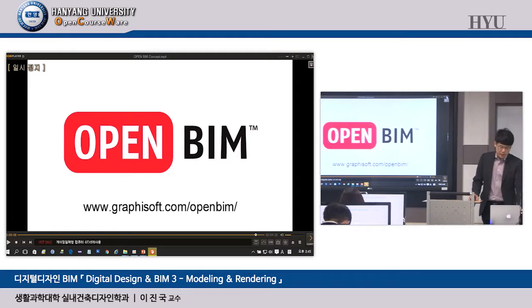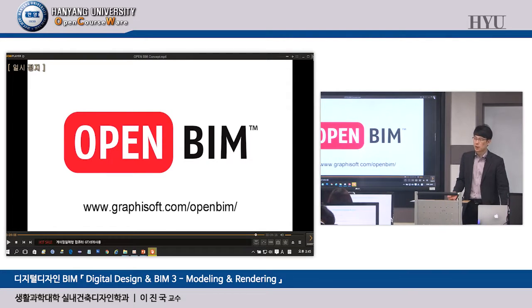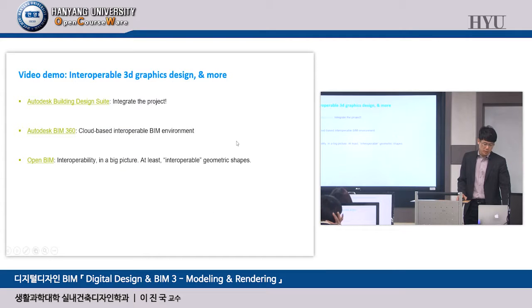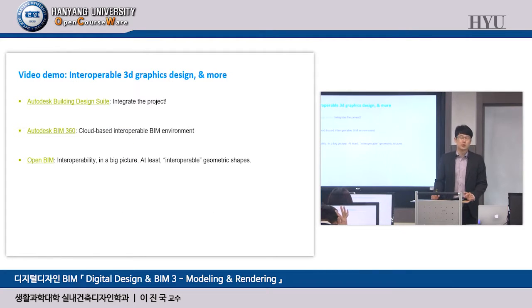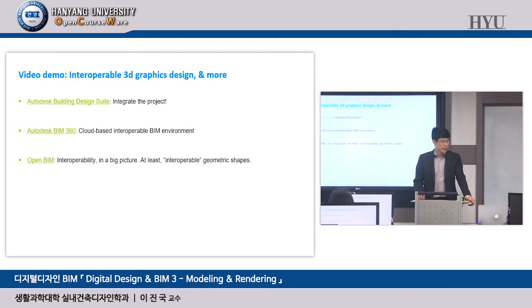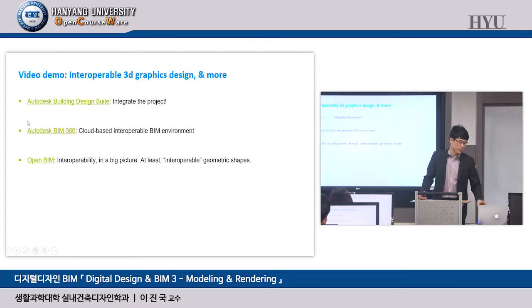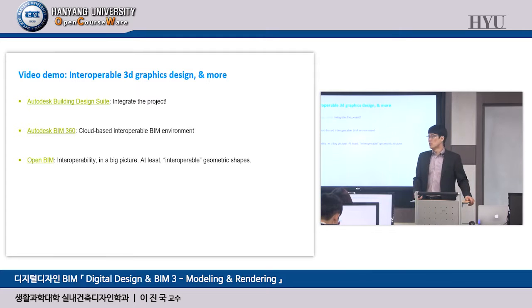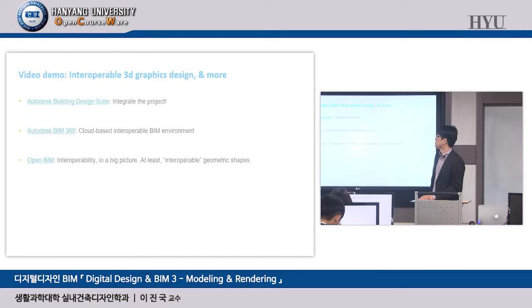Okay, Open BIM. In other words, Open BIM means IFC, Industry Foundation Classes, which supports the entire building information model, including geometry and associated non-geometric data for the building, okay? So that's why IFC is the one single neutral file format in the BIM domain, okay? Of course, there are Revit files, ArchiCAD files, Bentley files, Digital Project, CATIA from Dassault Systèmes, lots of BIM tools with their own commercial files, but there is only one single file format to contain everything and be shareable in this domain.